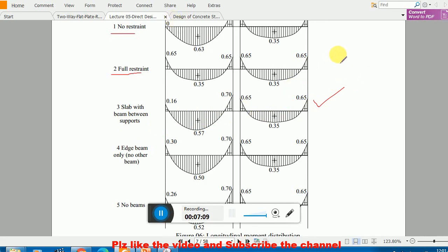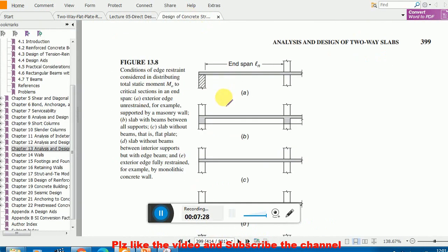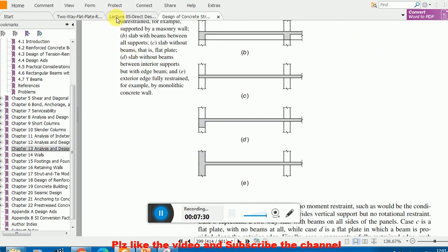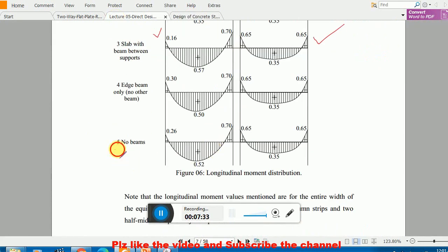Remember, this is when you have beams all over the slab system, all the panels covered by beams. We have perimeter beams and interior beams, so in that case we will use these coefficients, and today's example basically uses them. Similarly, here you see the case when you have no beams. We have already covered example number 1, 2 and 3, in lecture number 9. I covered two examples on these coefficients, so we are familiar with them.